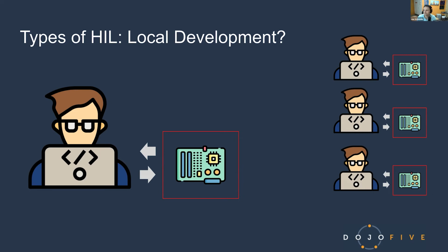So yeah. We had a couple of questions. Okay. So Dave just mentioned to everybody they build the unit tests into the embedded app so they can be run on the hardware, and they also build the embedded app as a Win32 app to use as simulated hardware, which is a different spin on HIL. And I've seen both of those. Those both seem like pretty common practices. And thanks, Dave, for that.